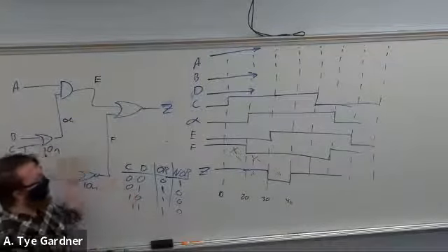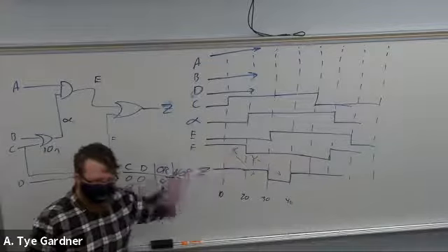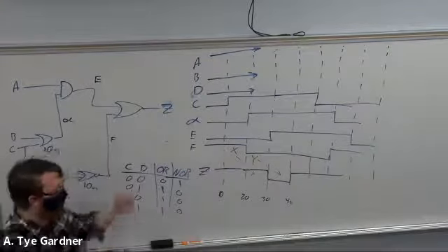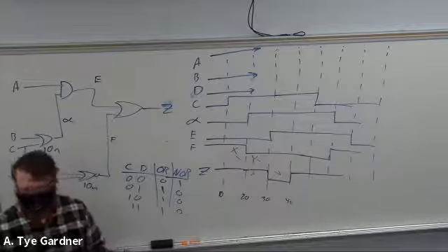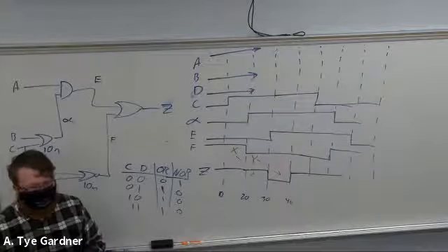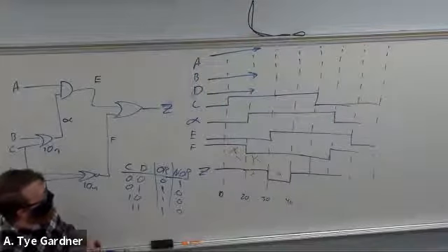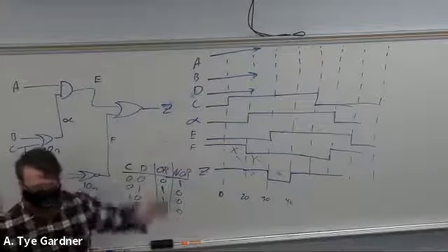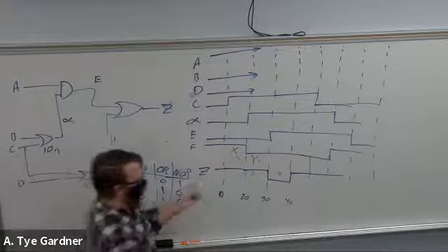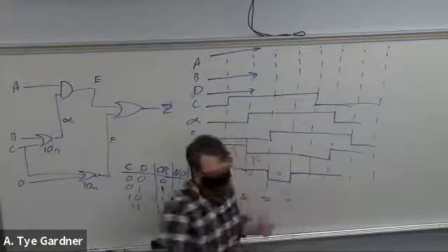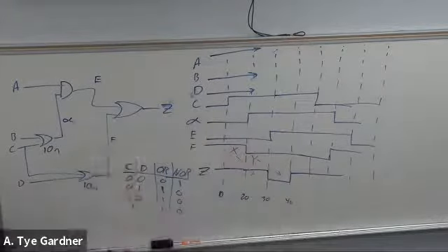So I would just find the major delay path and do one segment longer than that so that you have a guaranteed settling time. All that means really is worst case. I mean, this is as long as it's really going to be. It won't be much longer than twice this, just by nature, unless I have a really big circuit to make it worse than that.